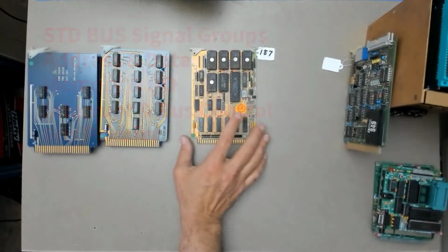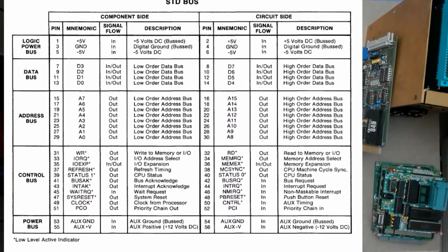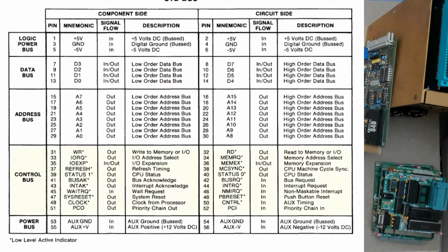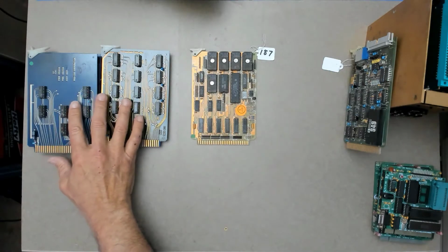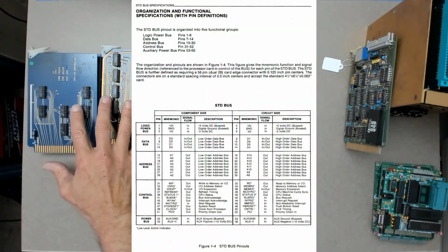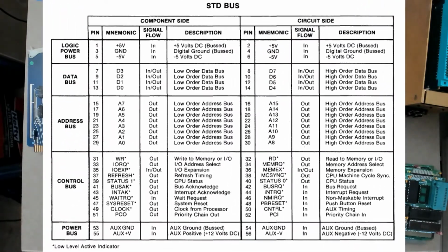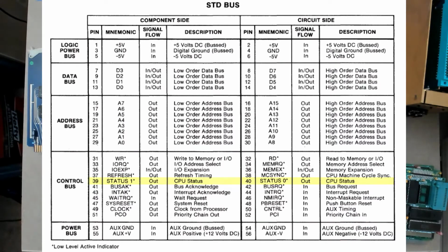To me, the most curious part of the collaborative effort is the bus signals, which were much closer to the Z80 than any of the Intel products. And that's interesting because, while the standard was devised by Prolog, Prolog's experience up until the STD bus was all Intel based. Intel had dominated the Prolog history and product line at that time. But in fact, versions of the 8085 S0 and S1 are about the only contribution of the 8085 that made it into the STD bus.